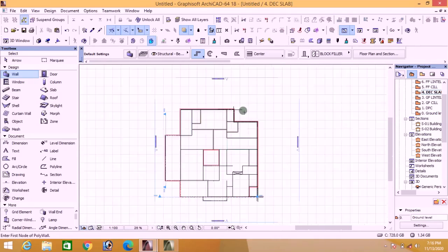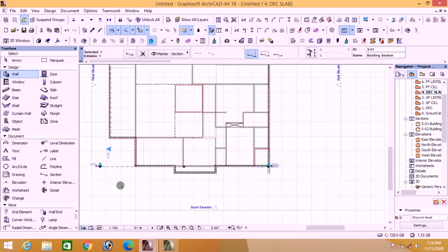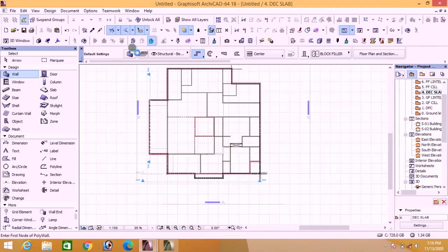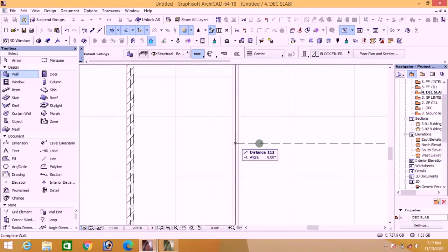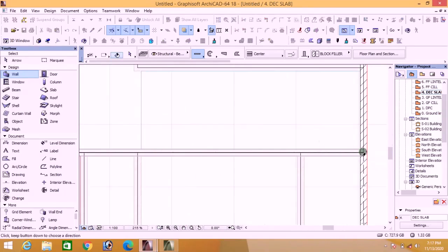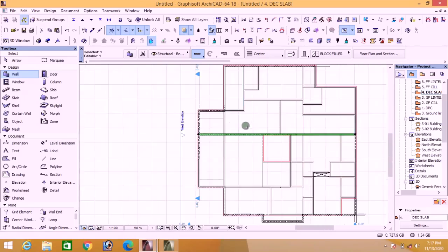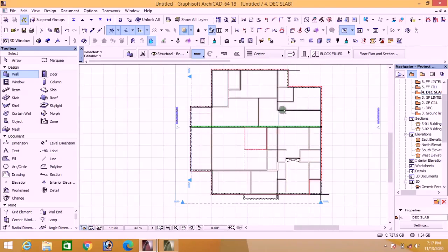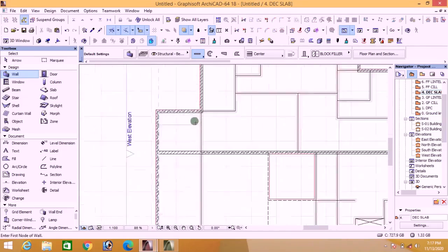Having done that, the next thing to install is the internal walls this time around. Let's install the internal wall. So we change this to single wall and start immediately. Let's take from this spot and extend this wall. As for partitioning, use your own discretion, as you want the rooms and the facilities you have here. As you want them, you decide. You design this type. Now let me show you what I have in mind for this place.